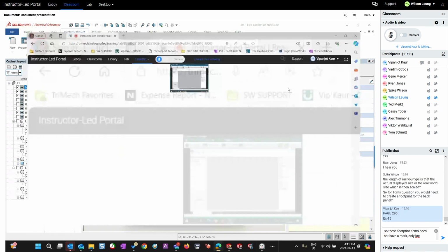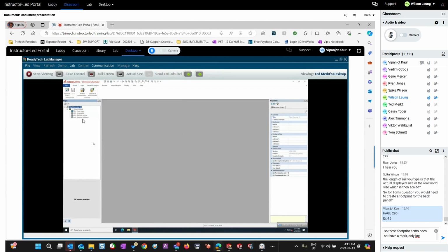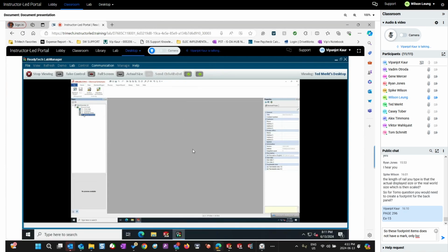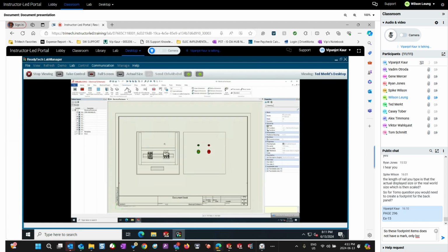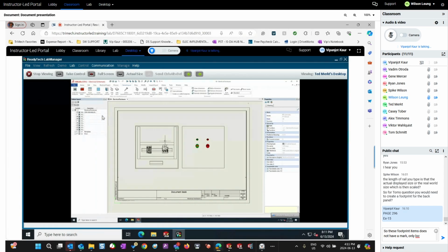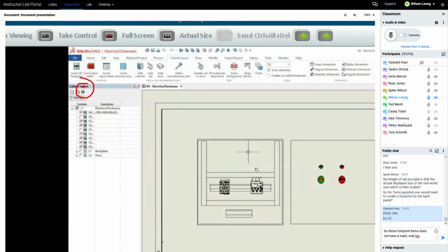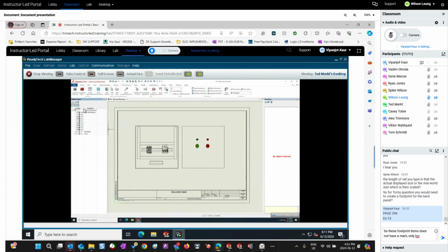Thank you. So go ahead and open up your drawing number 4, electrical enclosure cabinet layout drawing. Double click. It opens up a new tab on the top, cabinet layout tab. So they've done some work for you. Now, on the left hand side, you see this new component tree. Can you expand it from the middle line so you can read the names of it? Right after the symbols text, there is a small vertical line. Can you expand this so you can read the part number?